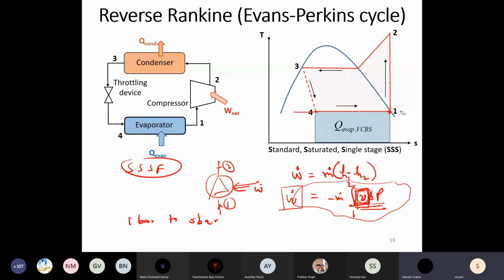Now, unfortunately, in a refrigeration cycle, your expansion process becomes the left-hand side one. Here, the density of the fluid is more towards the liquid side, so it would be significantly dense if you are expanding the refrigerant over here. Your V would be very, very small; densities are high. So what you gain here using a turbine would be a minuscule fraction of what you give to the compressor on the right hand side.